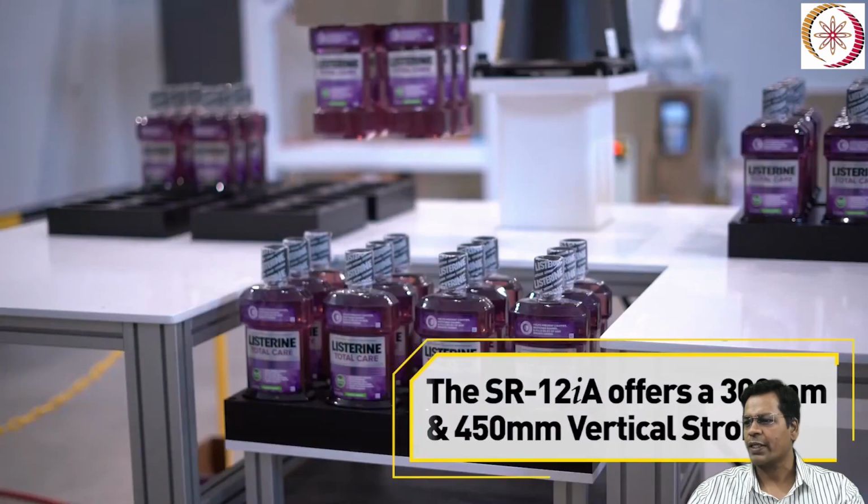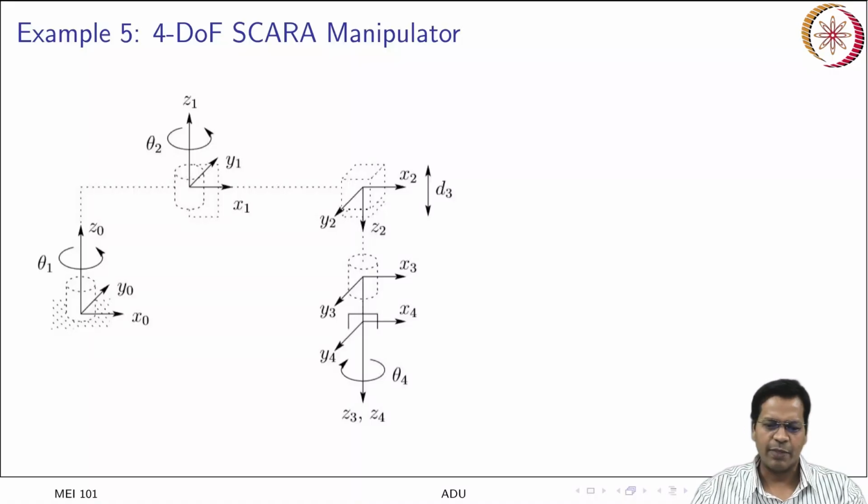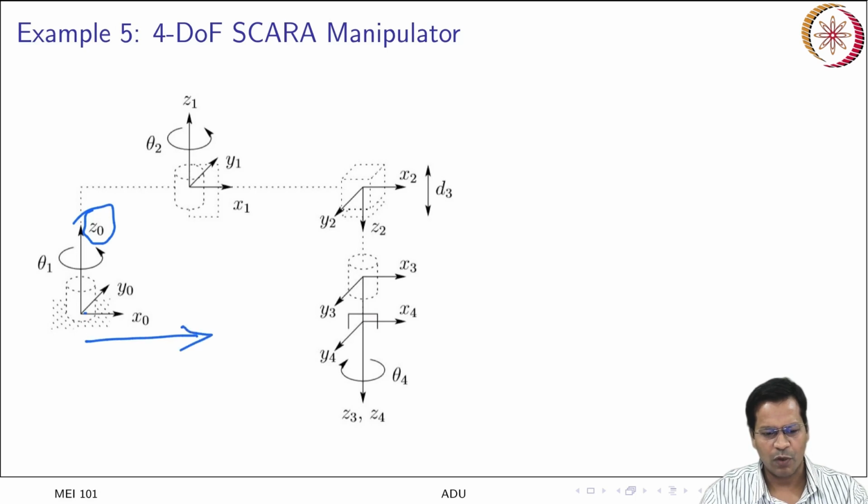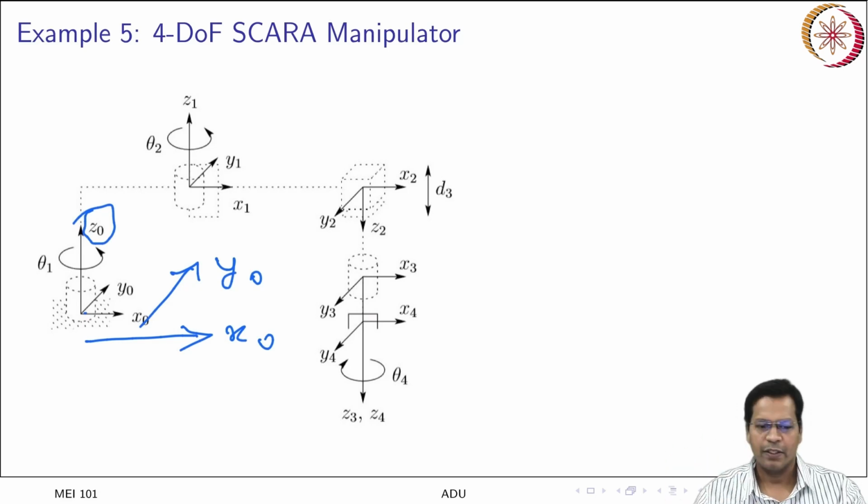Okay. So now let us again come back to the original kinematic picture. Although it looks quite boring here, it is very important in order to put DH and do forward kinematics. So let us quickly do that. You have the first axis, the vertical one, that is Z0, which is shown here. I have kept the ground frame like this: X0, Y0 and Z0, about which the first link is rotating. This is the shape of your first link.